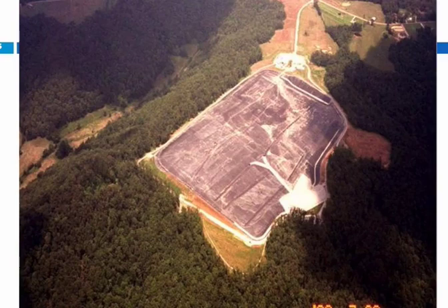The picture on this slide is an aerial photo of the site that was taken in the early noughties, early 2000s, showing an interim cap that was placed over the site consisting of an exposed geomembrane, similar to what we heard about before, an exposed geomembrane application that included some stormwater control features to try to prevent the infiltration of stormwater into those shallow trenches and the subsequent percolation and carrying of radionuclides away from the site. That was only an interim measure. It was always envisioned in the long-term cleanup of the site that eventually a permanent cap would be constructed once it was understood the degree to which subsidence would affect future performance.